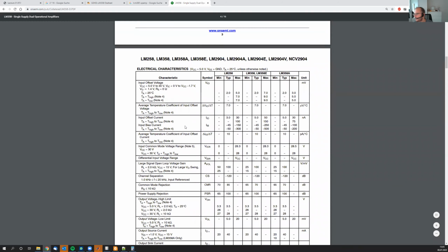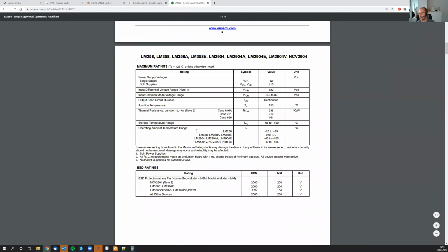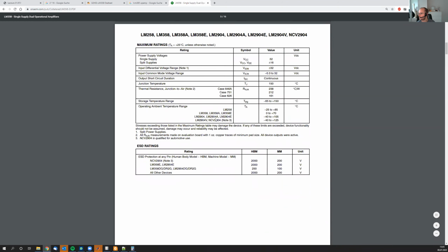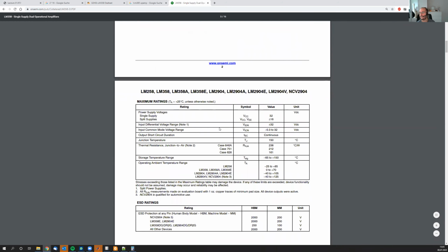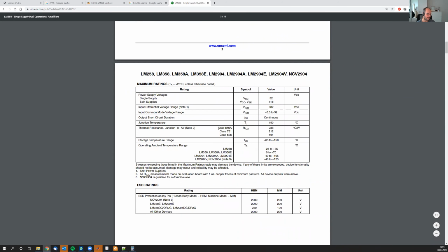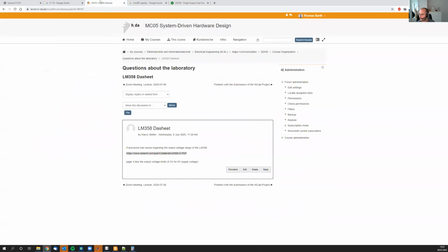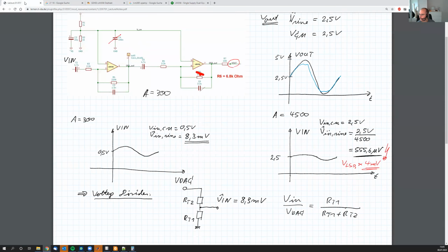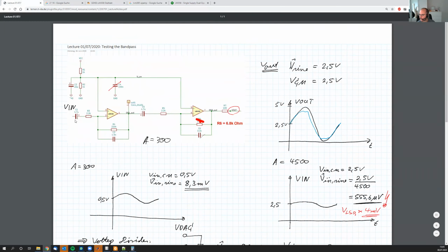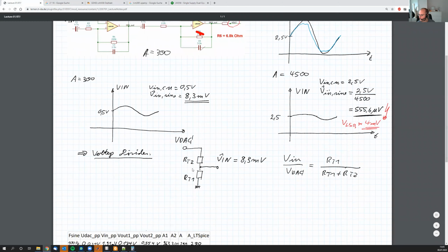Yeah, okay, but I'll leave that a little bit up to you, because this is unfortunately a very common task, okay? You design a system, you have to use a component, and you have to read the data sheet, yeah? And you really have to find the value you're interested in. So my recommendation here would be to really look into that, maybe read the data sheet, look for the characteristics you're interested in, and then we can decide what kind of voltage divider we need here to bring that voltage down.